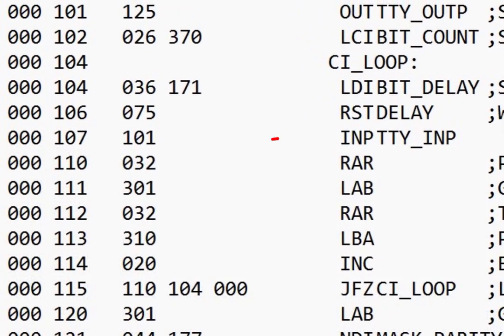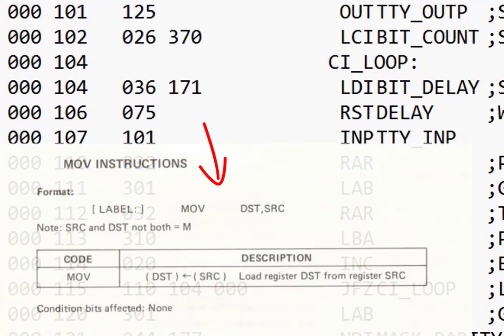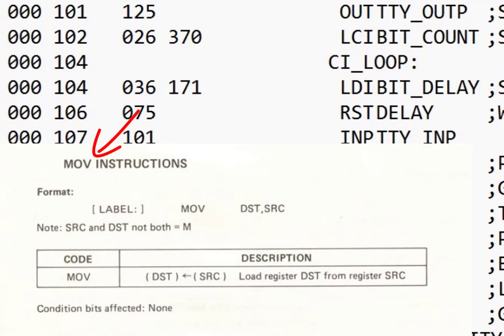The assembler has a little trick up its sleeve, because sometimes what appears to be a 2-byte instruction, with a mnemonic and an operand, can actually be reduced to a single byte. Let's take a register move, for example. The 8008 has old assembly mnemonics and syntax, and it has a new mnemonic and syntax. If we look at the new assembly mnemonics and syntax, you would have something like this.